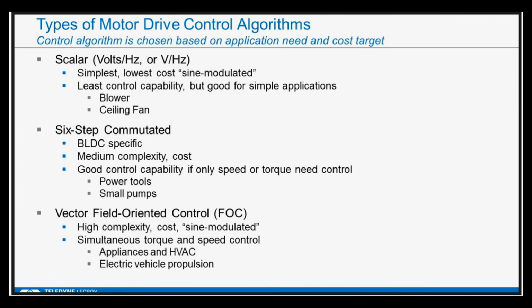When you get into high performance, you'll typically hear a lot about vector field-oriented controls, or FOCs. These are high complexity and cost. They're sine modulated technology. They're very good for simultaneously controlling torque and speed. They're becoming lower cost, but it can be a very complex system depending on the application.